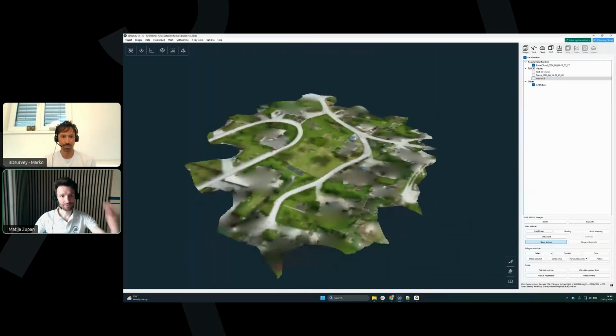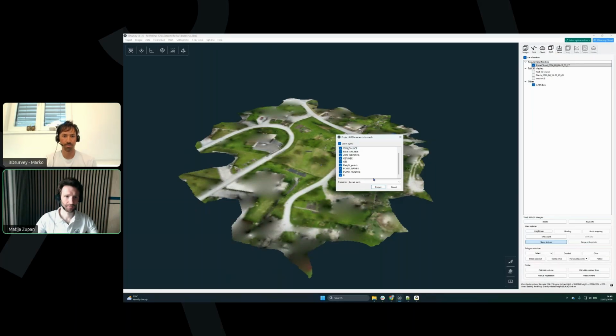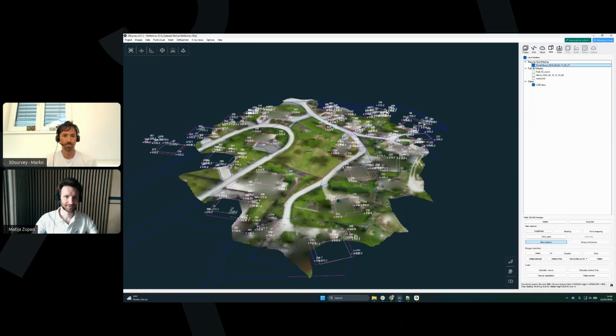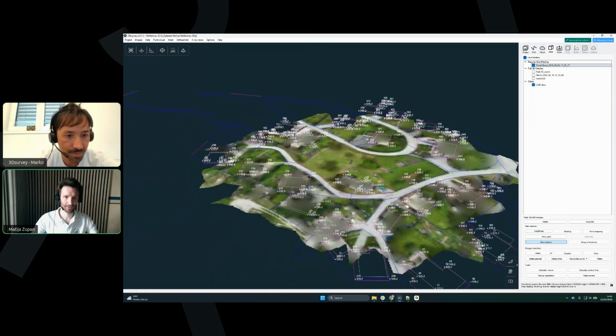Now I want my cadastral input data to be on this level. So if we check out 517, let's go to this regular grid mesh, right click, project CAD to mesh, all the points I have, I mean all the layers, project, and it's there. Now this is perfect. I can start working on this.